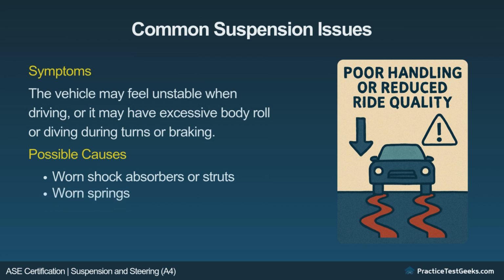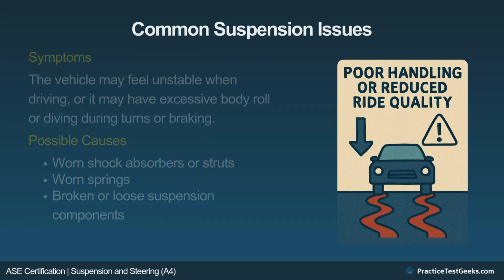Worn springs. Coil springs or leaf springs that have lost their tension may result in poor handling and reduced ride quality. Broken or loose suspension components. Any part of the suspension that is loose or broken will affect handling.